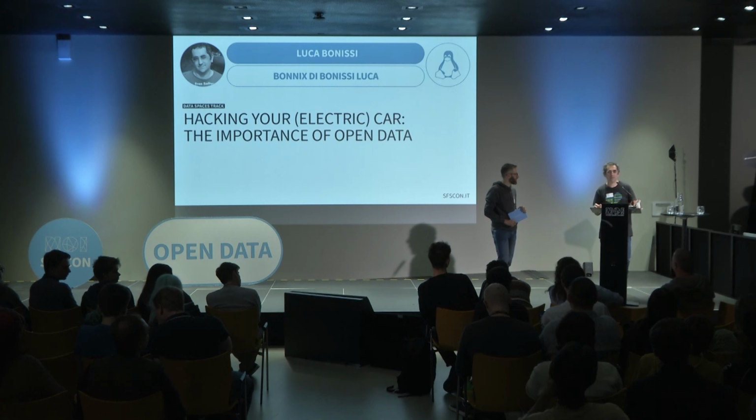Okay, in the trip that I made from Milan to here, I connected a laptop through an OBD2 adapter, a USB adapter, and I get raw data of the scanned PIDs. First of all, one time I leave the car power on for maybe 3 days, so that they scan all available PIDs, and then I make a selection of the interesting PIDs, and I get all raw data during the trip.